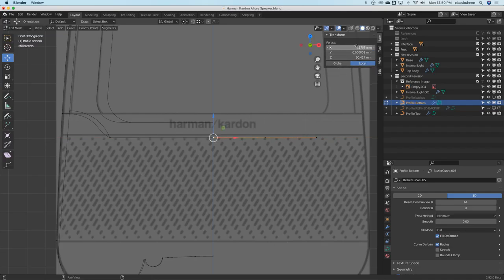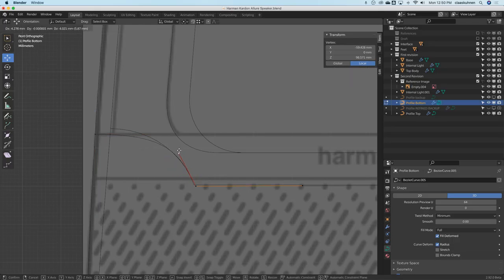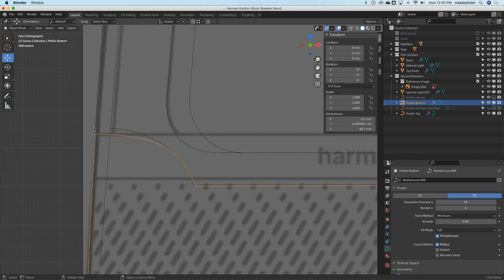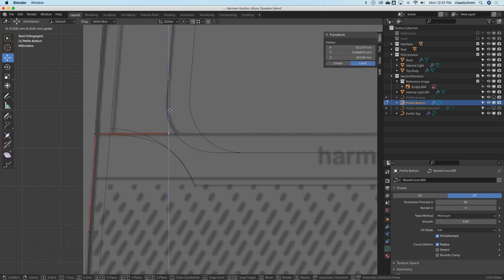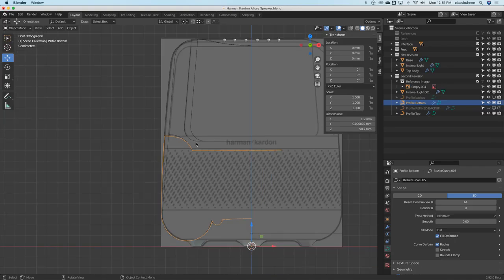This point should be X0, Y0, Z. Well, let's say Z90. We do the same here. Z90 minus 55. This has an arc, and then here select this point and arc. So we can shape this a little bit. I just snapped, dragged to it. Okay, there we are. Cool.